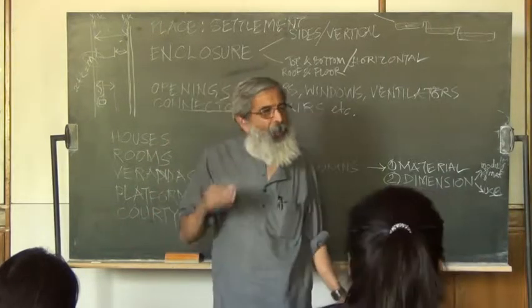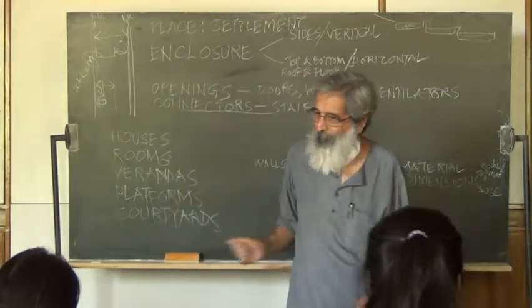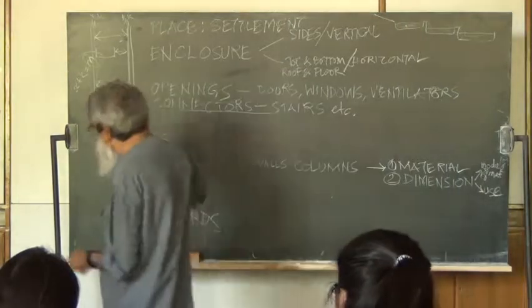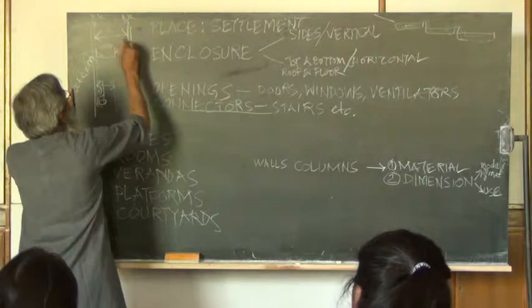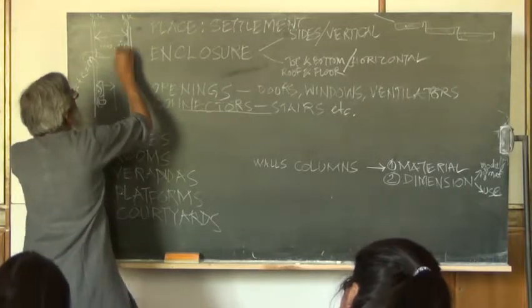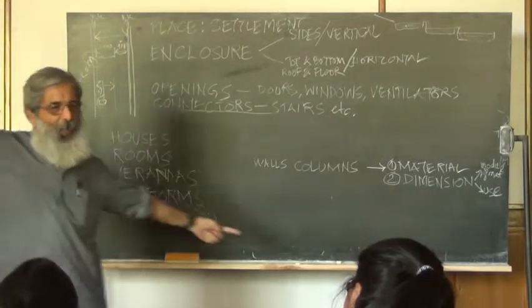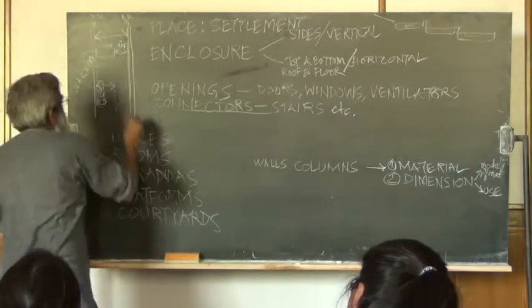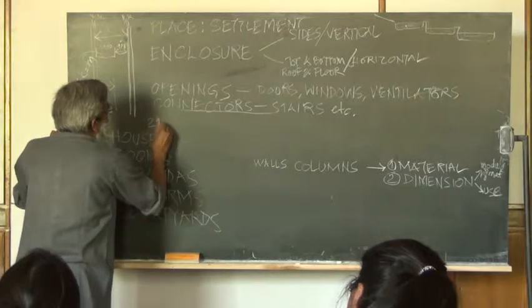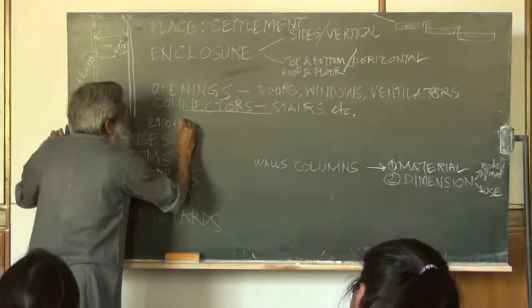Let me explain this with actual numbers. Say, if I have a bed of 2000 and I need 900 as a clearance, I need 2900 space. And if this is a brick wall which is 230, then I get 2900 plus 230.